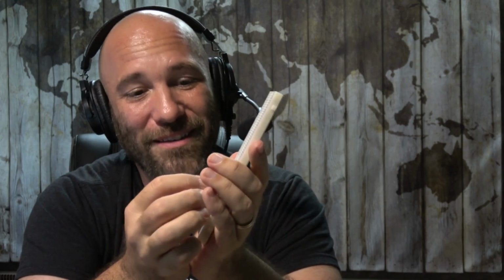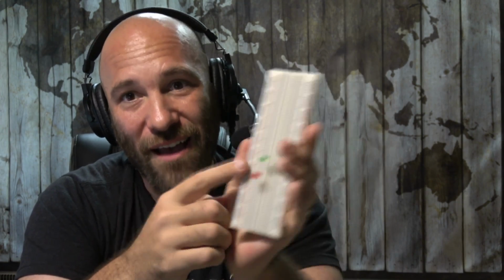Now, soldering is not hard, it's not complicated, but when you're experimenting, when you're playing around, you don't necessarily want to have to heat up the soldering iron every time you want to swap out something like an LED. So whenever you're dealing with Arduino projects, you're going to have a breadboard like this in order to connect all of your electronic components. And in here, you're going to be able to connect things like resistors. You're going to be able to connect things such as capacitors for your devices, LEDs, as I showed you.